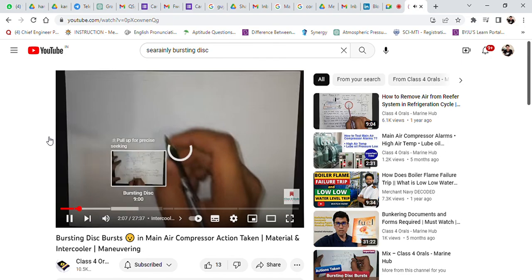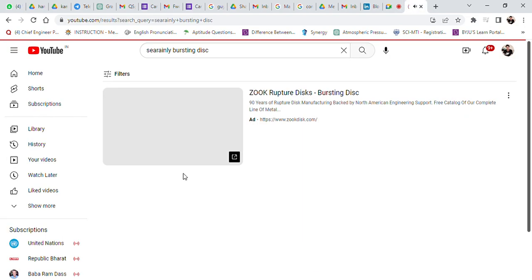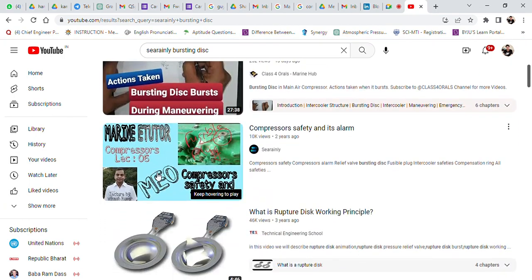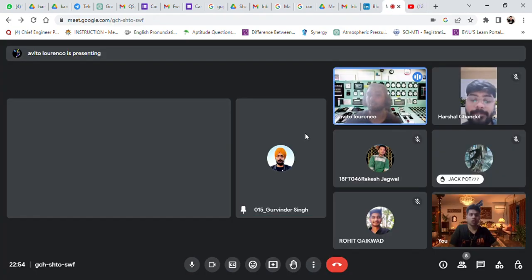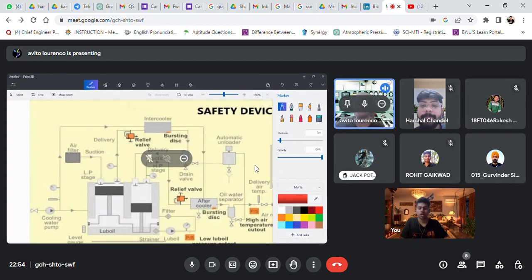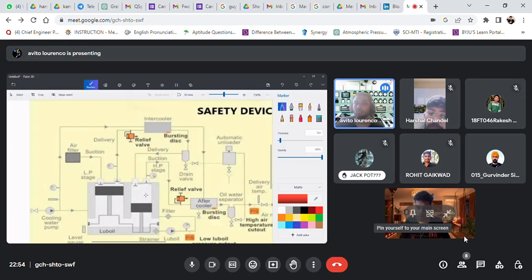So coming back, after the bursting disk, we have now completed representing our first stage compression plus cooling of this compressed air. From there we go into a drain valve. This is basically more of a bypass type of situation. Let's say for example I don't want the cooled air after the first stage to go into the second stage compressor, maybe some issue has taken place. I can simply activate this drain valve.